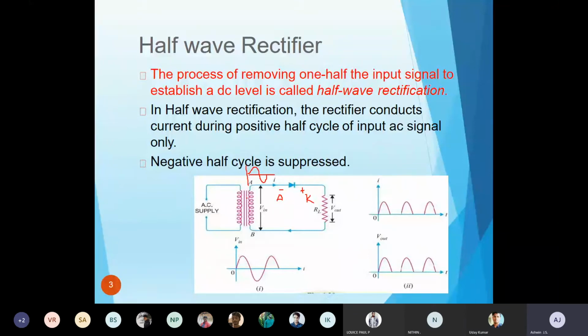So during reverse bias, will conduction occur or what? Conduction won't occur. Only in forward bias will conduction occur and current flow. In reverse bias, there is no conduction. It will act as an insulator, in the sense of an open circuit.